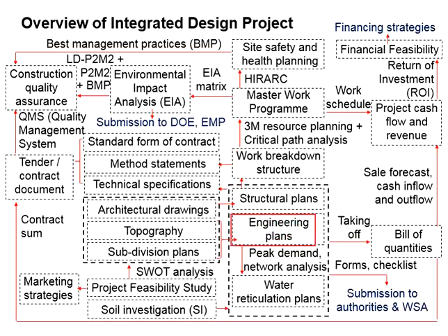Next, we talk about the engineering plans. Engineering plans shall be worked on the basis of the topography given by the land surveyor, as well as the subdivision plans as approved by the state planning authorities. The engineering plan will have to indicate the lot and sublot, as well as the adjacent lots, and indicate the roads, drains, slopes, the proposed elevations, as well as the existing elevations.